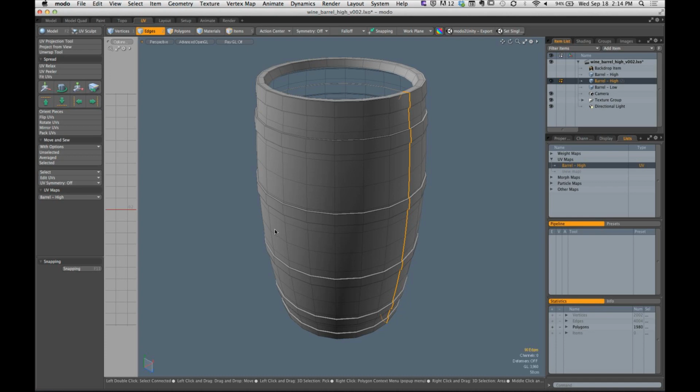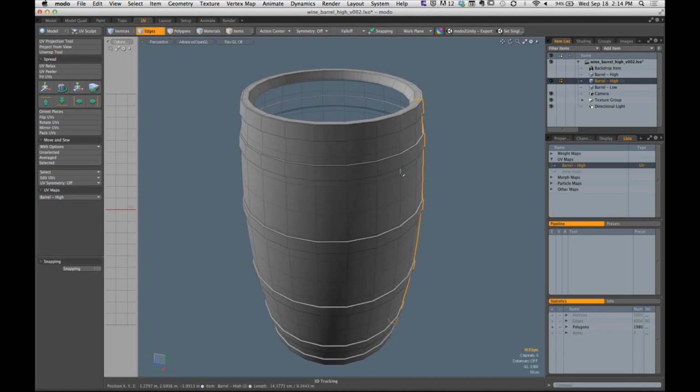Okay? I don't know about you guys, but 9 times out of 10, whenever I'm designing something in 3D, I very rarely see the back of things, right? We often show the front of all of our models. So where's a better place to put the seam for our texture? At the back. Yeah, Austin's got it. Okay? Along the back of our model as the starting point for the UV Unwrap tool.